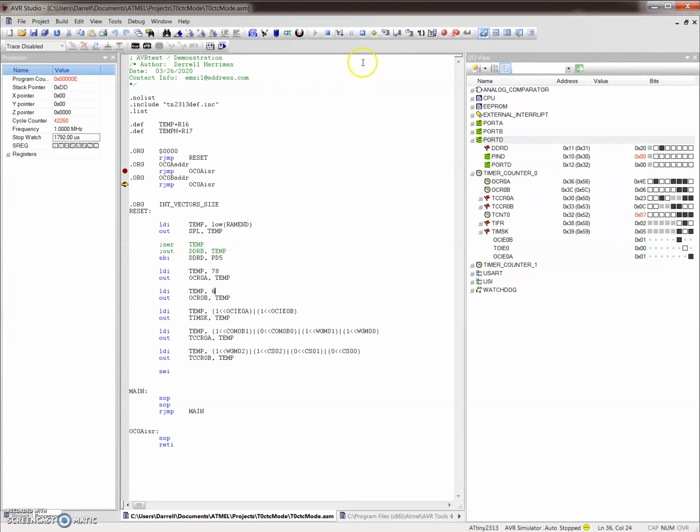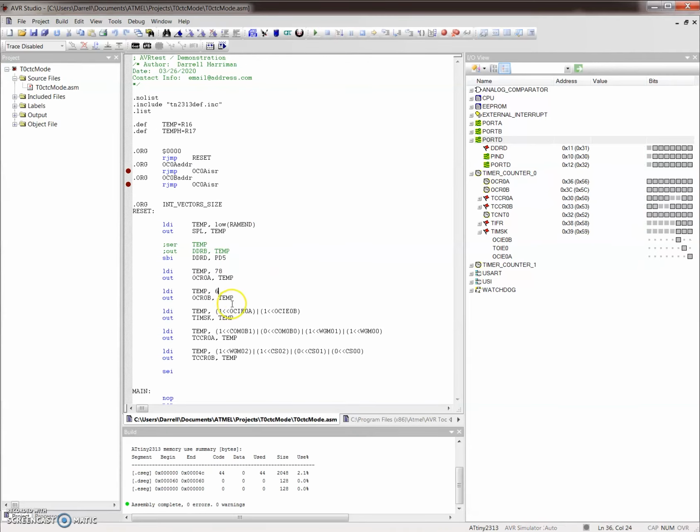So let's go ahead and make that change, and then we'll test it again and see how close we are. This one is a really small value, it's at 6. By reducing it to 5, that's almost a 20% reduction in our time. So that's pretty low resolution. We don't have very much accuracy on our control for the pulse width, which means basically to get good resolution, we need to go to the 16-bit timer and have a much higher resolution.